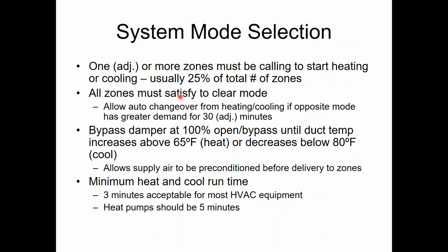Usually we wait till all the zones are satisfied before we clear the mode, and then we switch over to the other mode if need be, right? So we take care of the cooling callers. When they're done, we switch over to take care of the heating callers. Usually in the summer and winter, we don't have both, but in the spring and fall time, you do get some guys asking for different stuff based on sun exposure and time of year. We'll clear one mode before we switch to the other.